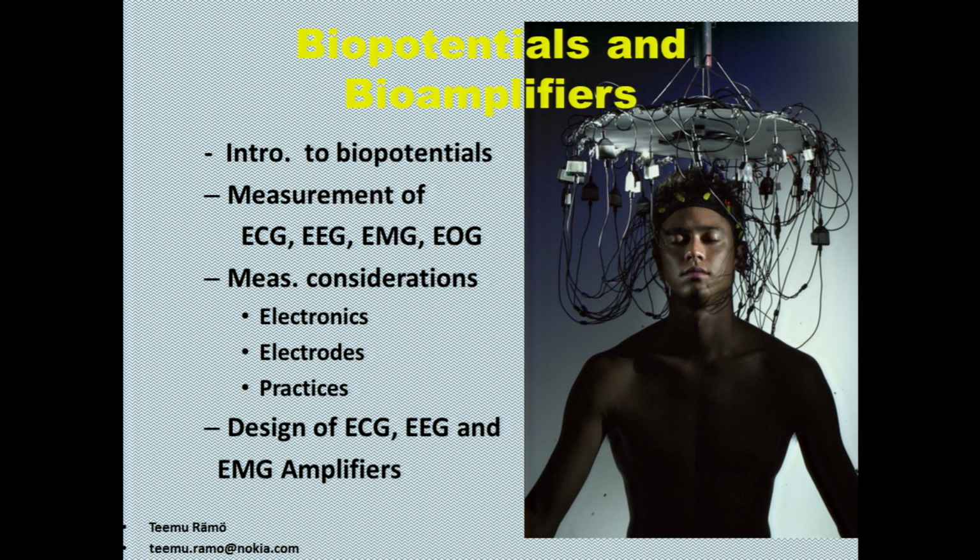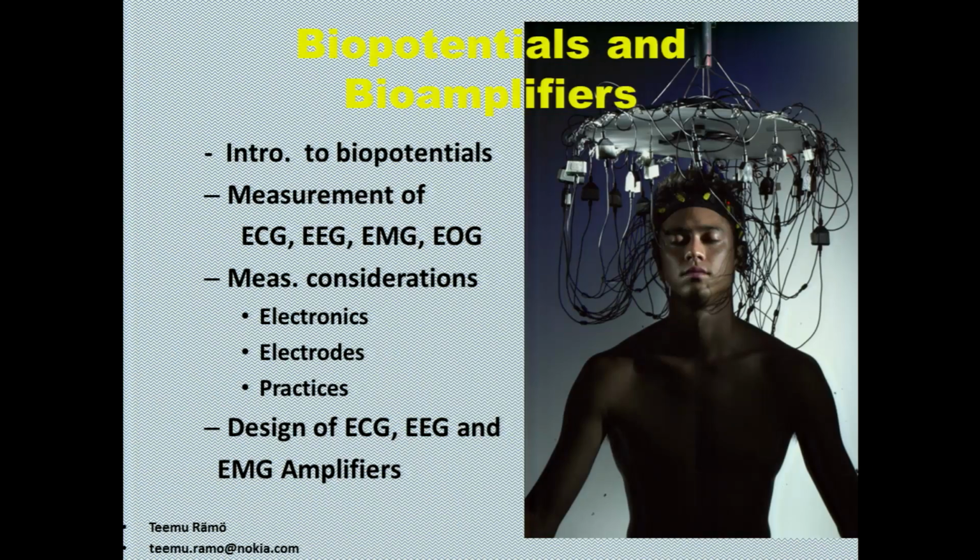The first 1 hour we will talk theory, next 1 hour we will do the designing of the ECG amplifiers. Basically everybody remembers op-amps, that is what it is: differential op-amp, instrumentation op-amp, and then one high pass filter, one low pass filter. To know why we want to use that, we will see.